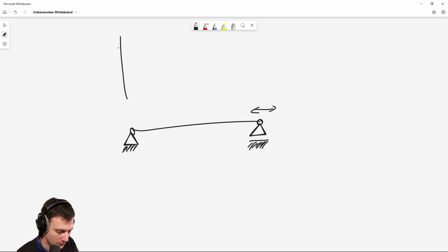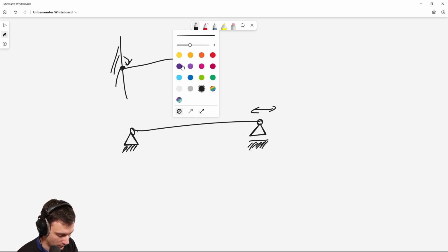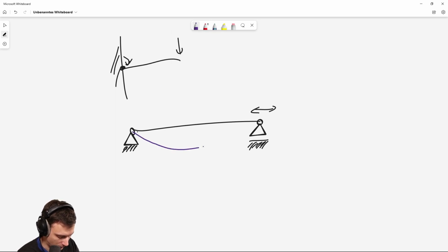So, for example, you have a beam which is fixated in a wall here. You can press down here and transfer a moment or torque on this point. You cannot do this with those bearings. So this is free to flex, just like this, for example. You see that the turning here will not introduce any force reaction. So just translational force transmission on these bearings, right?